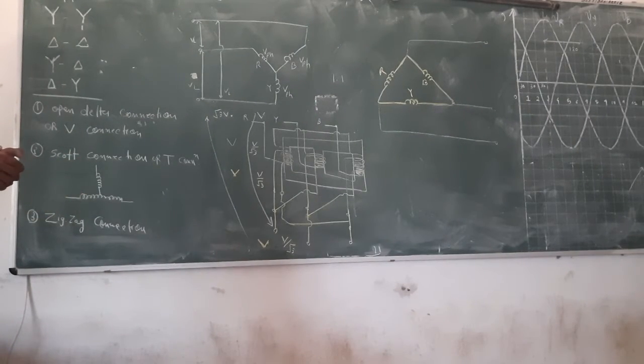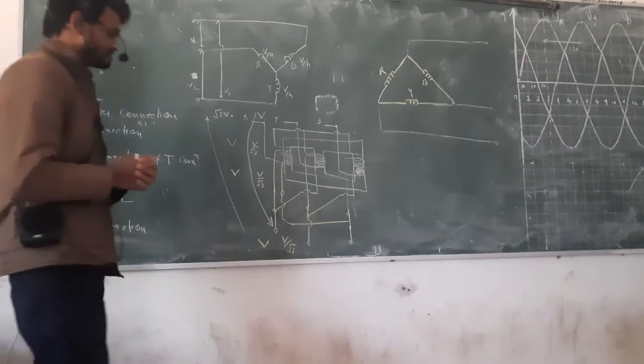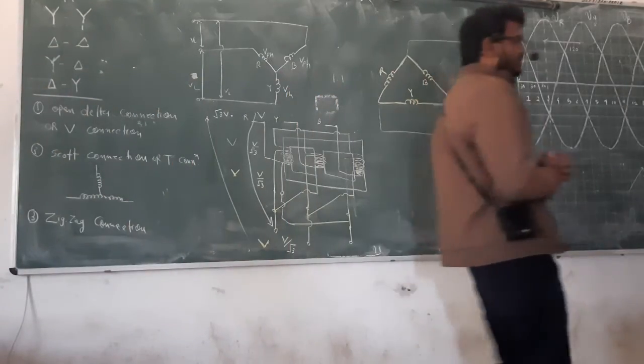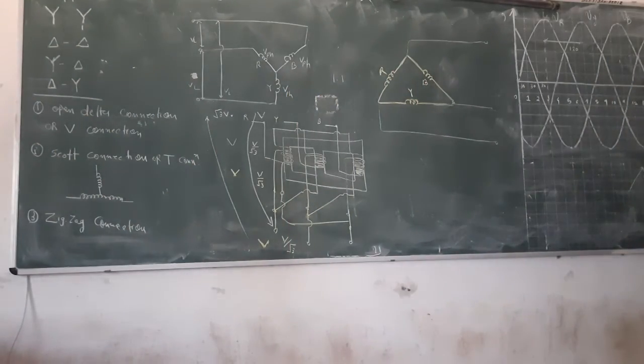Okay. So this is the core concept that is applied in real transmission line systems. But whenever you do this, there are benefits and some drawbacks. Let's say when you apply star to delta, a voltage rise or voltage fall by a factor of root 3 will be there.